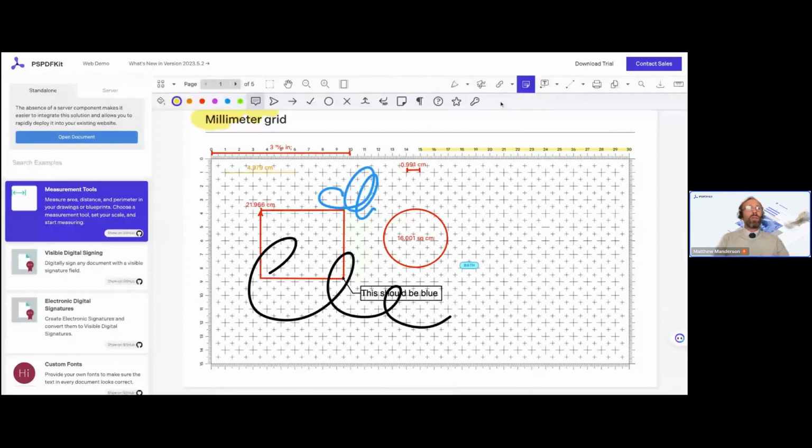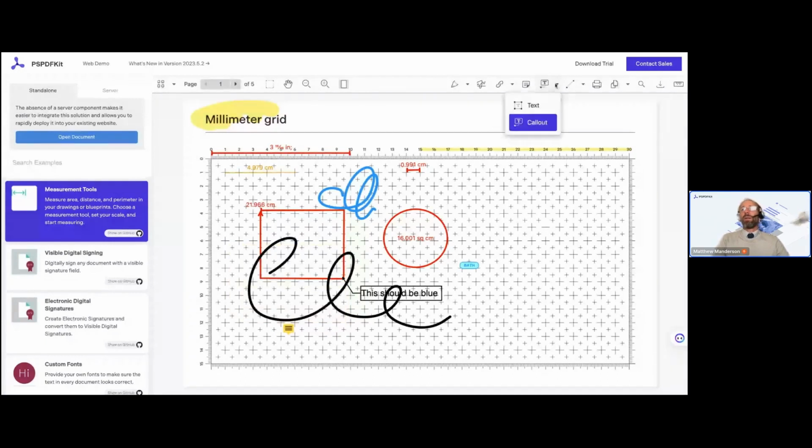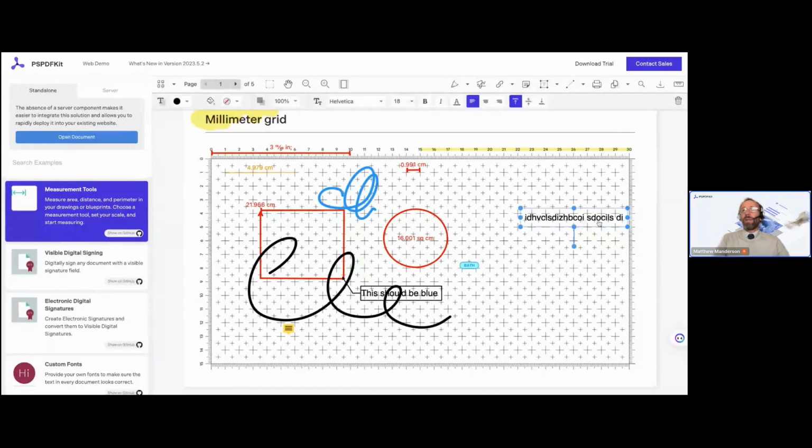We have these note icons. So this is useful for finding a place on the drawing, marking it, typing some text. These are basically exportable as well. So you can export these. That's now hiding in there. And we have a number of different colors, number of different icons you can use for various purposes in here. Then we have a plain text. So you can just basically start typing a text box here. And then you can do stuff with the text box. A lot of the annotations now in this year as well, you may not know, are also rotatable.